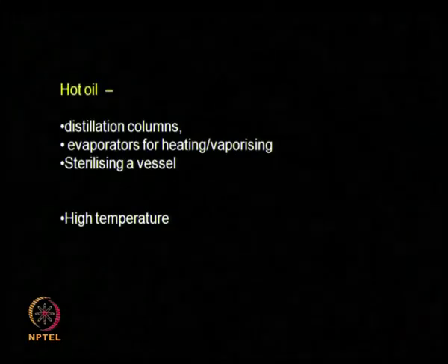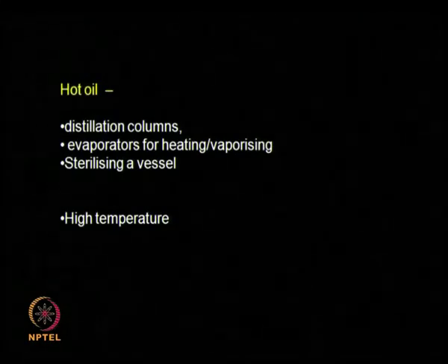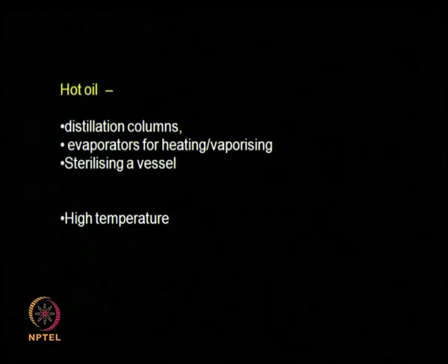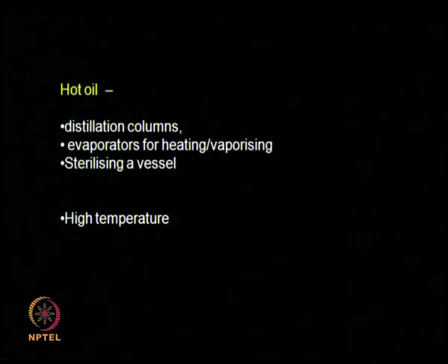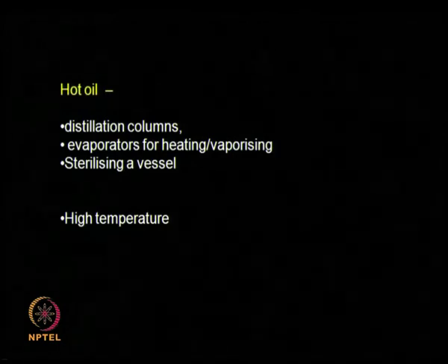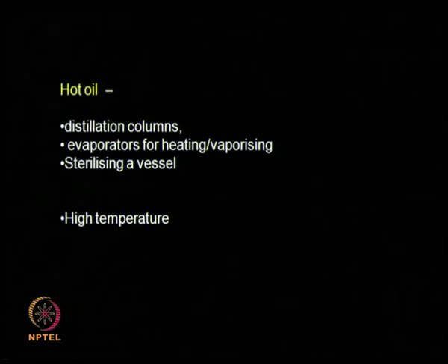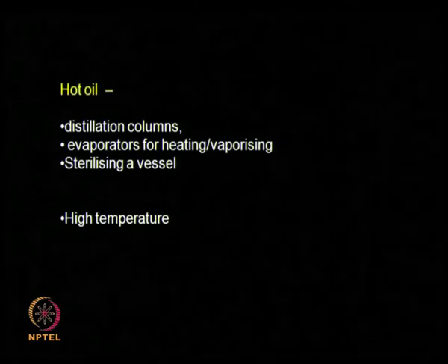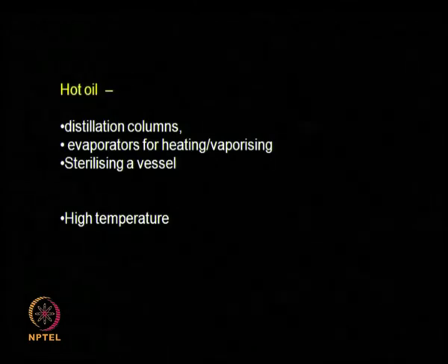Hot oil, if you want very high temperature, 180, 190 degrees, then hot oil is always preferred rather than steam. If you are heating distillation columns, evaporating, sterilizing vessels, the advantage of steam is you get very good heat, you do not need to recycle, the steam will transfer the heat and it gets condensed as water which could be recovered, whereas if you are using hot oil, the hot oil return line is very important.